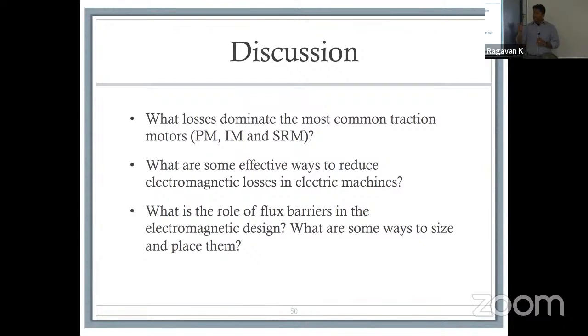But the idea is that when you're talking about fields, the biggest challenge, even for FEA, oftentimes is sharp edges. First and foremost, your analysis of sharp edges can be challenging, but more importantly, the design of your part for that motor can also be challenging. If you look at the Prius motors, you will see that they make a magnet, and at the end, in the slot, they have a little small notch.